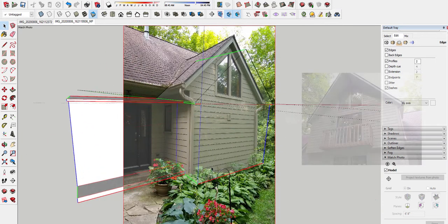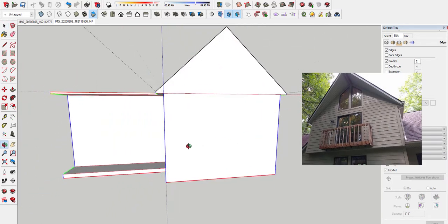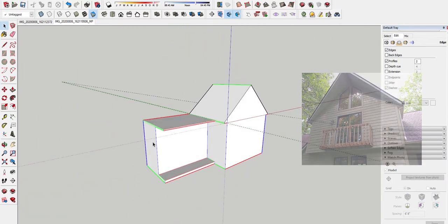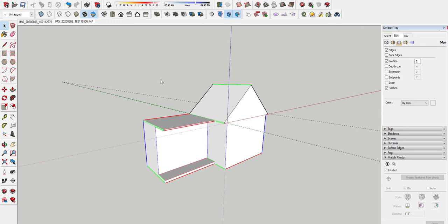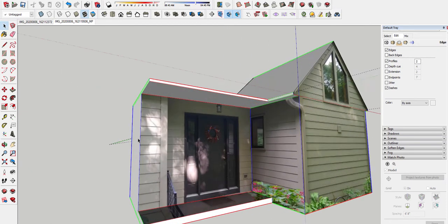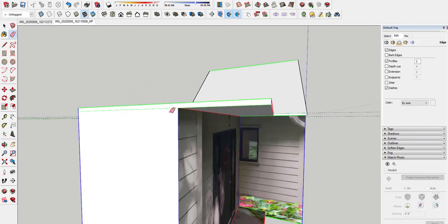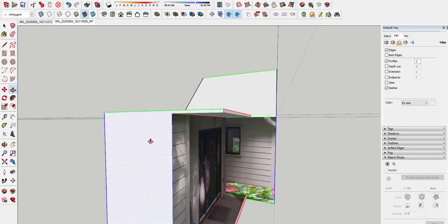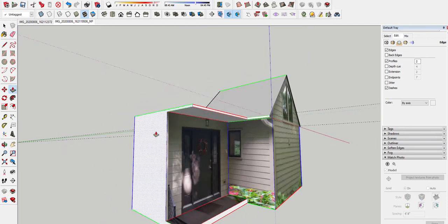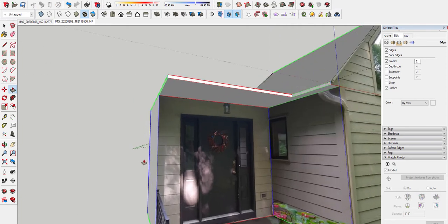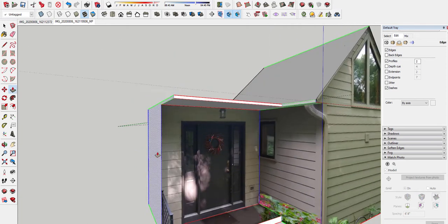All right, so the third image I'm going to bring in is actually looking from this angle. Let me make sure I have the image proper here. So I'm going to push pull this. Here, this line needs to be cleaned up. I'm going to push pull this to this point because I'm going to have that edge of that wall in my next image.